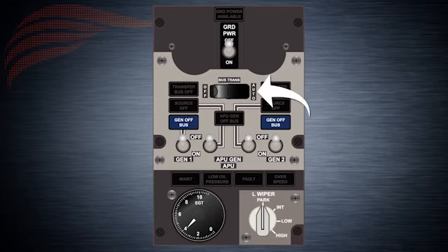A bus transfer switch is also present and works in a similar logic to the bleed air isolation valve. The isolation valve is covered in the air system's bleed air lesson. This switch has the following positions. Auto. Power is maintained to the AC transfer buses from any of the AC power sources. DC buses are connected or isolated as per the system logic. Off.